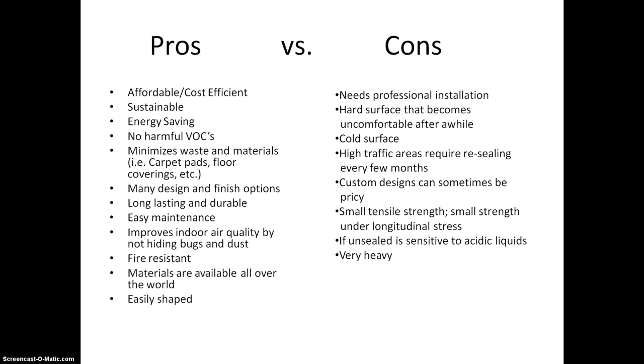The materials are available all over the world, and it is easily shaped. The cons to concrete is that it usually needs professional installation. It's a hard surface that becomes uncomfortable after a while of standing on it. It's a very cold surface. High traffic areas require resealing every few months, or even more than that if it's like in a mall or whatnot. Custom designs can sometimes be pricey.